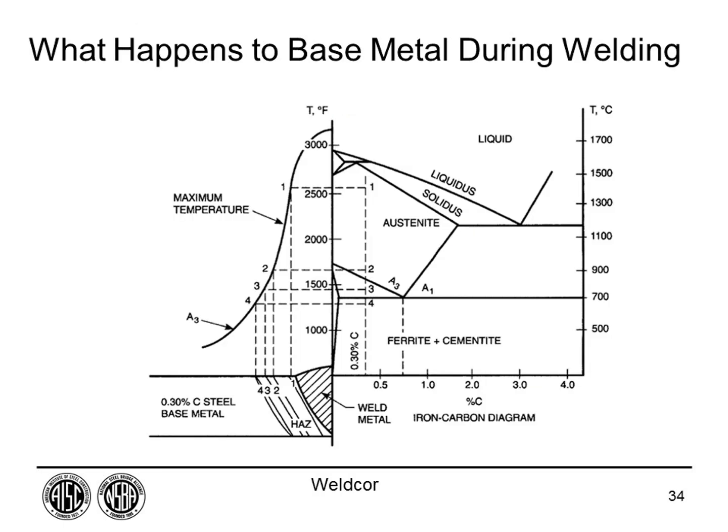So if you look now at a weld in that phase diagram, what we've got here is just half of a weld, and this part here is the part that was a liquid. So that's the weld metal. And the chemistry of the weld metal is a function of the base metal and the chemistry of the electrode. That's why it's important also to control the chemistry of the base metal.